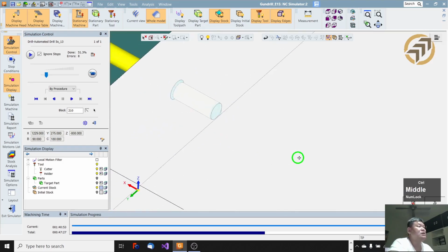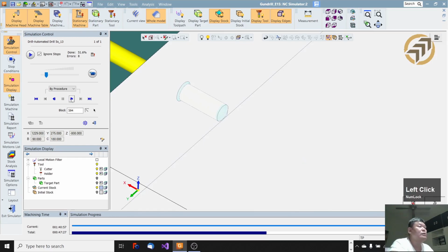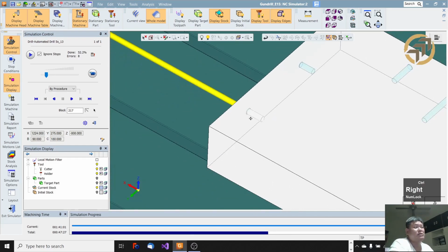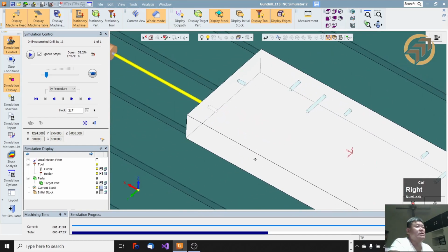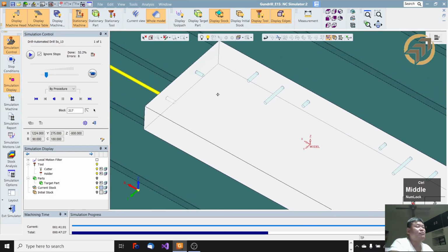So I'm going to zoom out here. This all you can set in Cimatron. Yeah? So 5 mm guide and drill until here with 50% feed rate. After this 5 mm, next is to drill to the full depth because there's no cross hole here. So you will drill to the full depth with 100% of the feed rate.